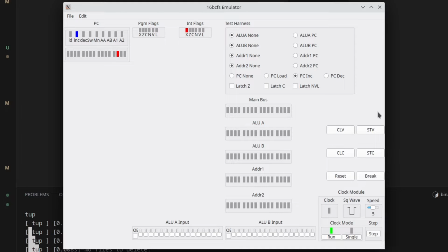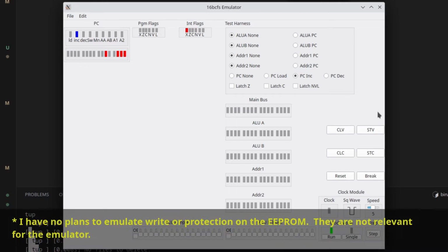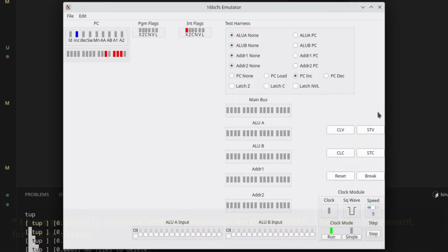This now tees up the emulator to be able to read the control ROMs from that folder and load them up into memory. Now the control ROMs, as in EEPROM, are going to be emulated just as a file. And then I need to emulate the read instruction where I shift out the individual bits from the EEPROM so that they can be moved into the actual SRAM.